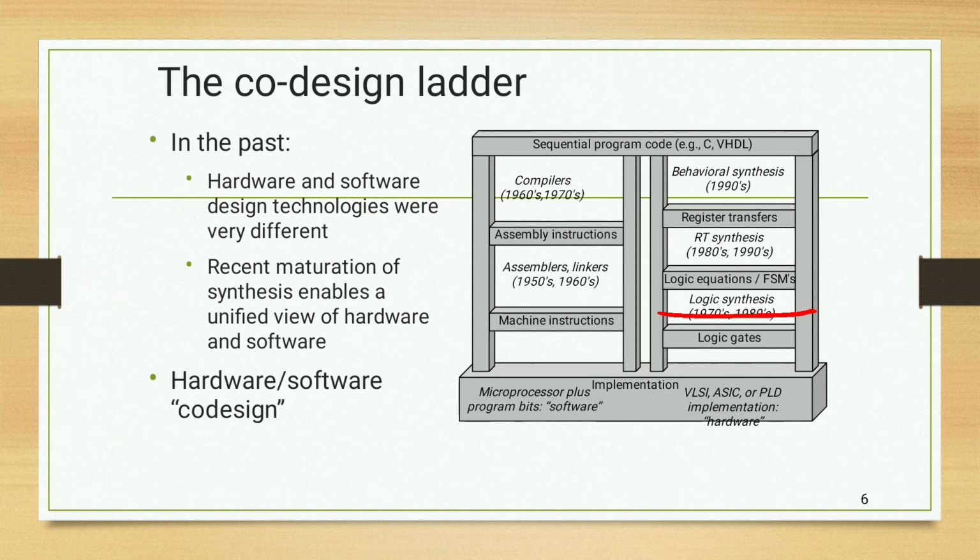A register transfer, that is RT, synthesis tool. This is done, logic synthesis, now RT synthesis. A register transfer or RT synthesis tool converts finite state machine and register transfer into a data path of RT components and a controller of Boolean equations.